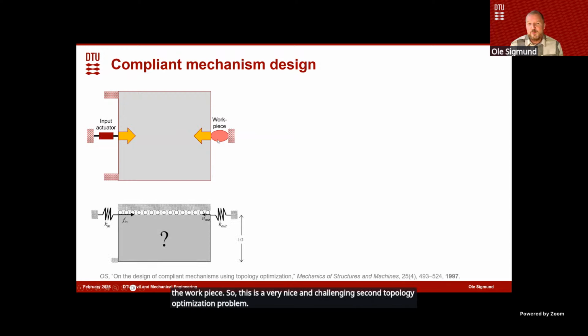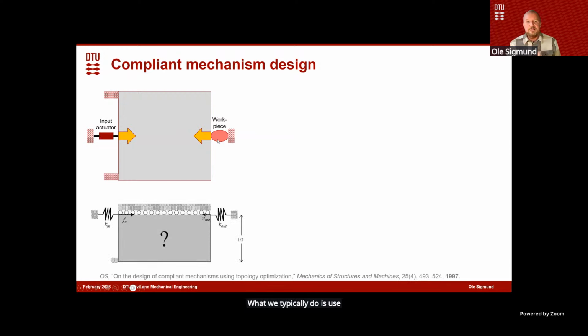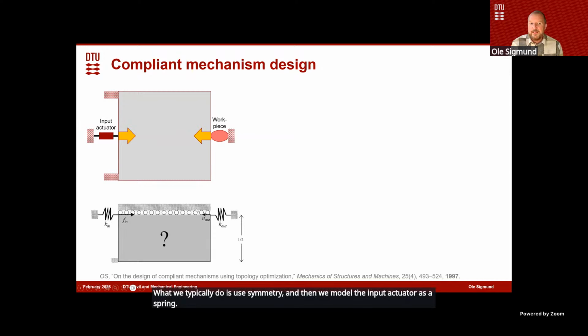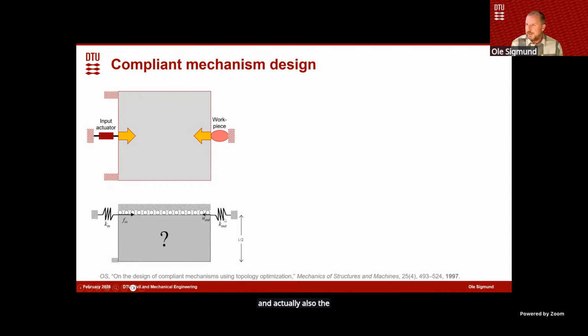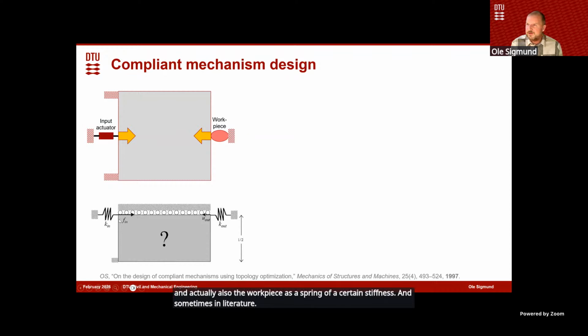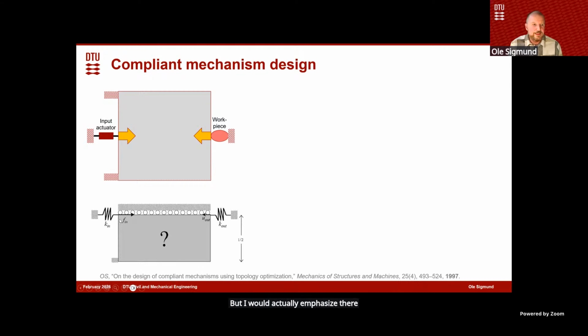What we typically do is use symmetry, and then we model the input actuator as a spring, and actually also the workpiece as a spring of a certain stiffness. And sometimes in literature, these are called artificial springs, but I would actually emphasize there's nothing artificial about these springs.